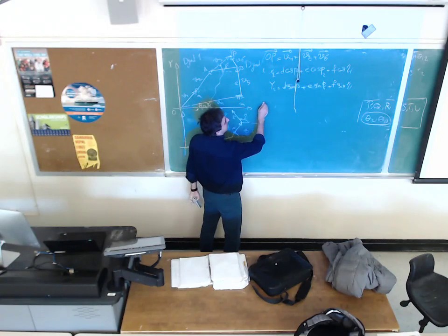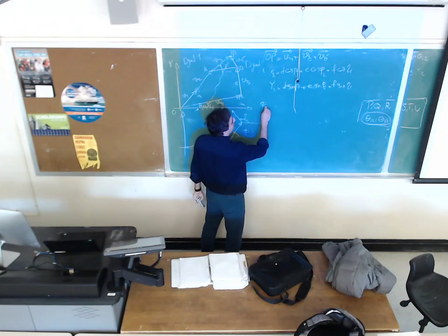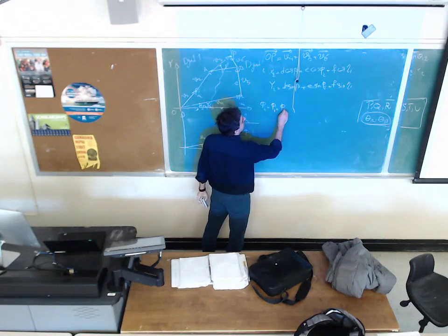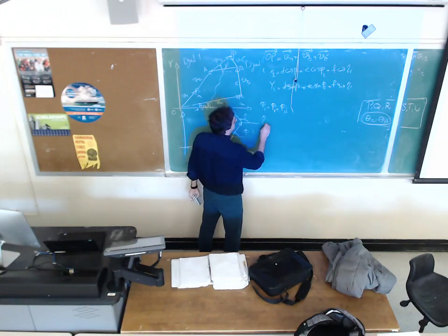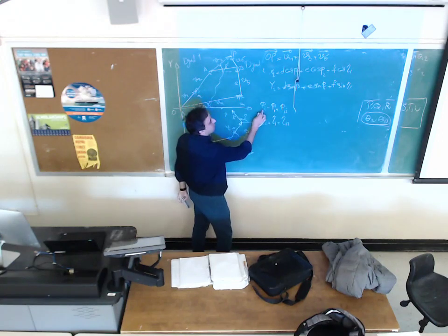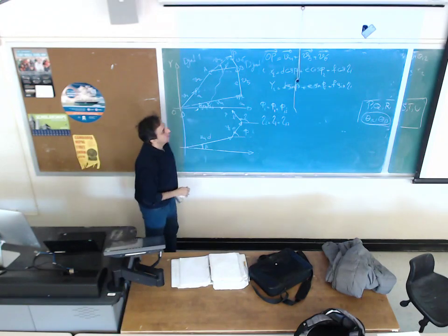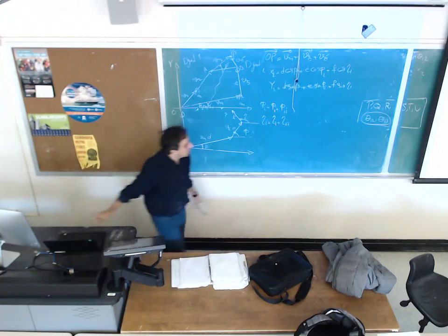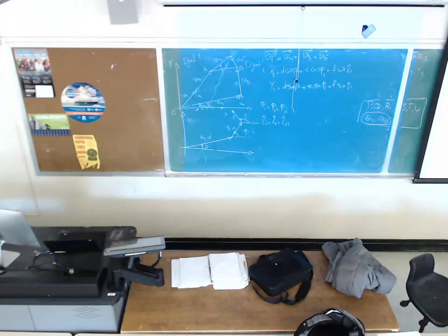Again, same as the left-hand side diad, we write phi_i equals phi_1 plus phi_1i, and eta_i will be eta_1 plus eta_1i. We write every equation with respect to the first precision point. Then the equation is going to change to this. Instead of having phi_i, we are going to have phi_1 plus phi_1i, and eta_i should be replaced by eta_1 plus eta_1i.